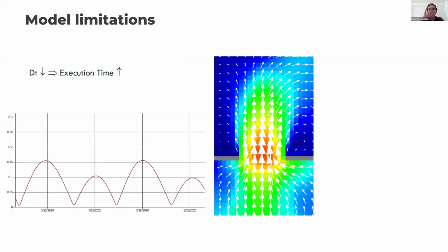So I'm showing you here an example. This was done with the model that I will be using in the presential session. You see this is the flow. The color is the velocity modulus, and the vectors are the velocities, in a bar of an estuary or a barrier island. So a tidal system, and the tide is going up with a certain velocity, and we have the maximum velocity here, okay?